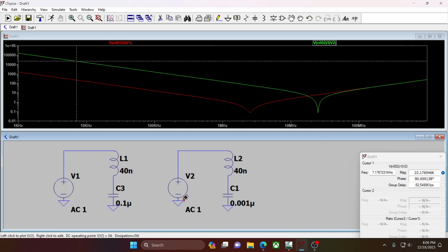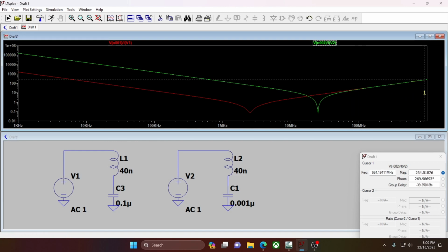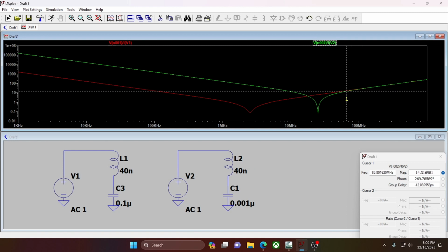We're at a huge difference between these two for capacitance, but at higher frequencies, around 100 megahertz or so, about right here, 50, 60, same thing. So at around this point, lower values don't do jack. It's like they don't even exist. But at the lower frequency end, oh boy, they make quite a bit of difference.